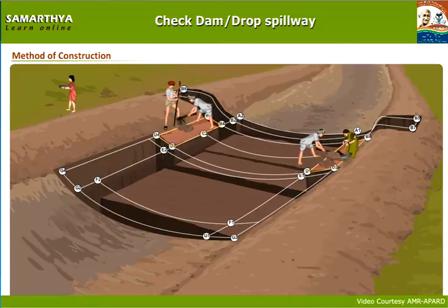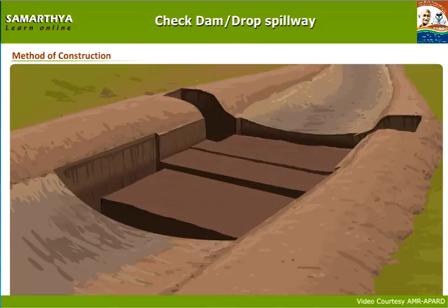At the center of B3, B9, D3, D1, B4, B10, D4, D2 with 0.60 meters width from top of the stream up to foundation levels of body wall, dig foundation and deposit the excavated soil away.